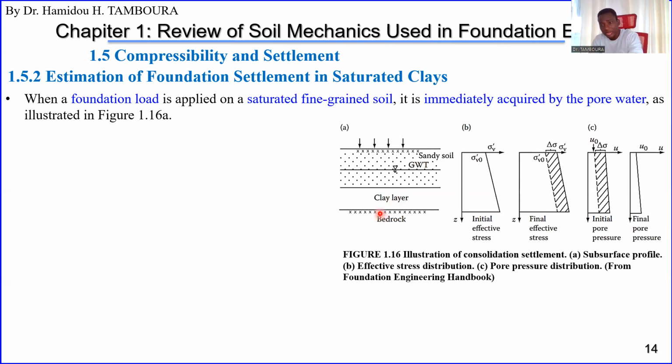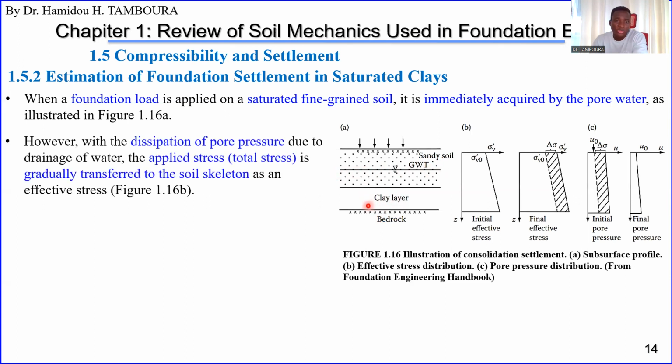Once you have clay, saturated clay, it's saturated because the water level is here and clay is here. So if you have that, when you load, the load is immediately taken by the pore water, the pore water pressure, okay?